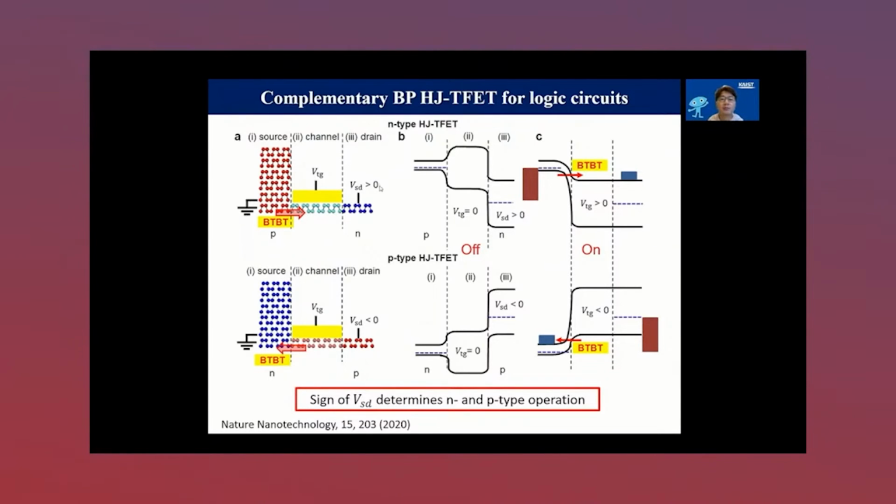So for the positive bias voltage, due to the capacitive coupling between the graphite and the monolayer BP, the band in region 3 under graphite, here monolayer BP band, shifts downward. And then what happens is we need to apply positive gate voltage to make band-to-band tunneling occur. So it turns on at positive voltage and negative voltage it's off. So it's basically N-type TFET.